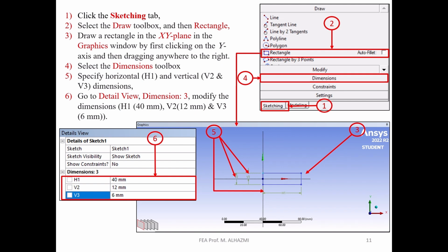Create the geometry sketch. Create the geometry in the Z-plane using basic shapes. Begin with a rectangle, define its dimensions, then add circular holes, and define fillet radii as required. Trim unnecessary lines and arcs to clean the sketch.